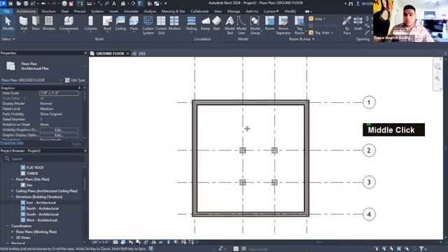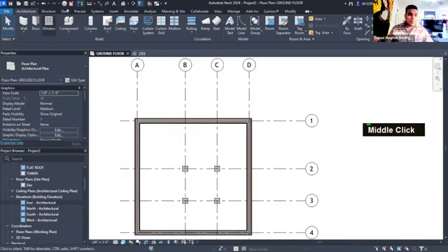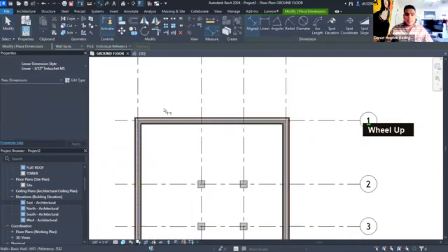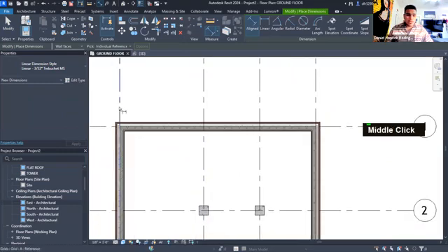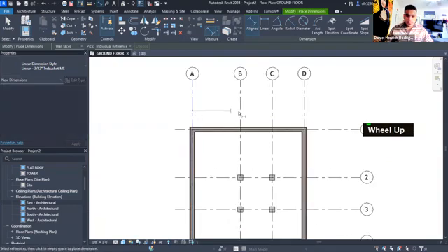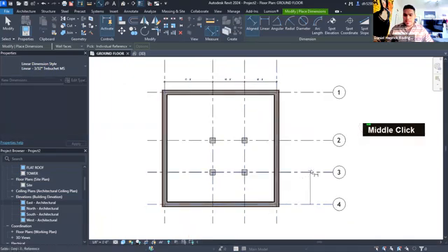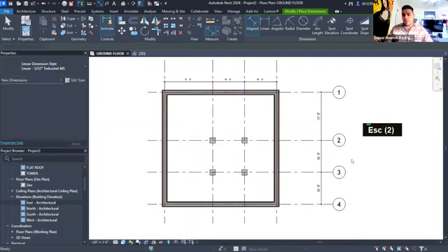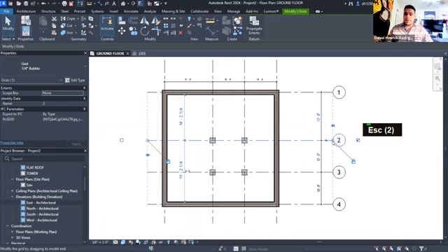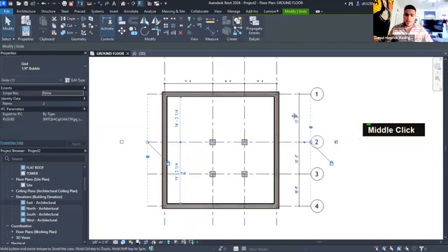In this case, these walls perfectly line up with the columns, with the grid lines, because like I said, the purpose of this model is to just be an introduction. But if they weren't to line up with the grid lines, essentially you have to think this way. So grid lines are absolute. As long as you have your grid lines properly measured, everything can be measured off the grid lines, right?